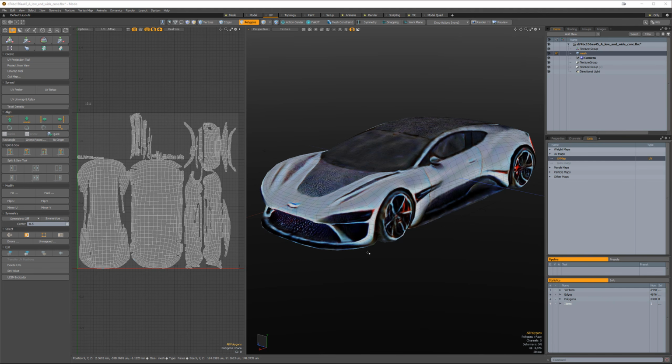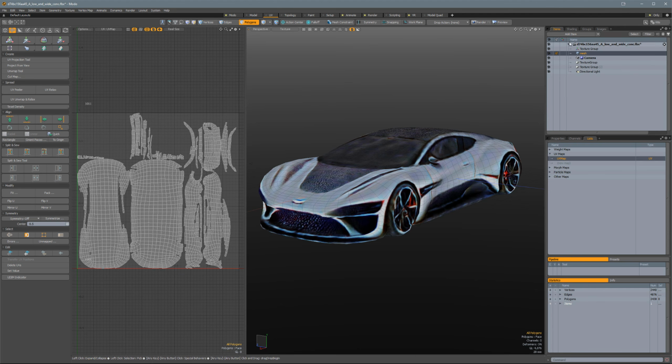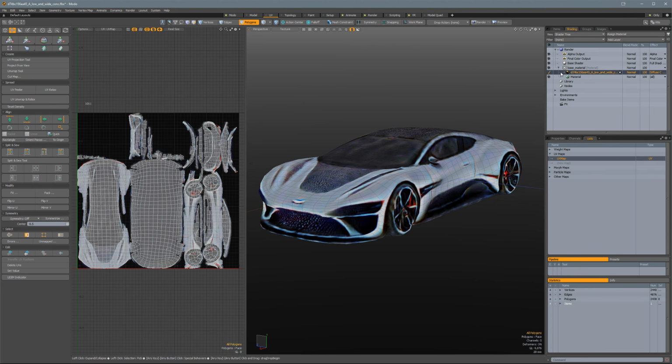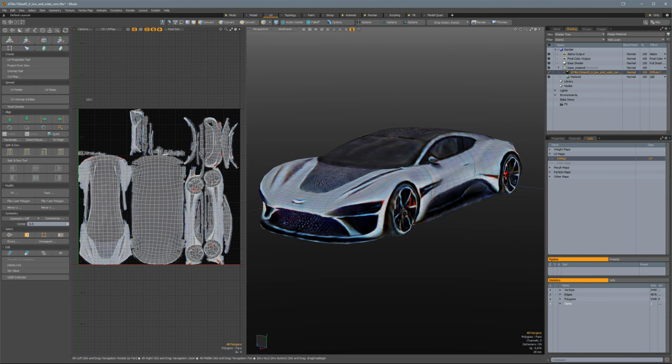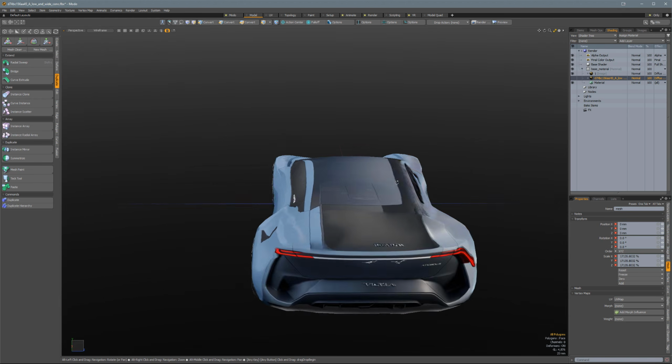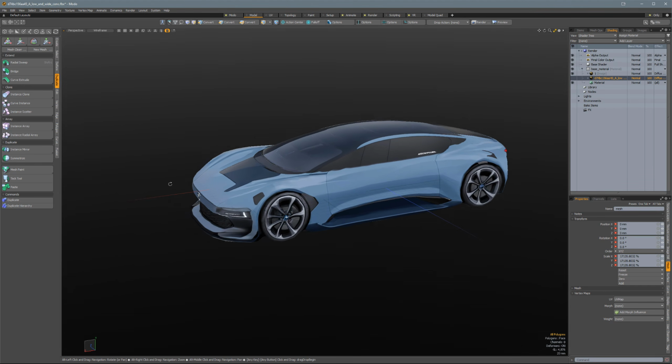So now I've just opened Modo, and I've imported the FBX file that we downloaded originally from Genie, as well as the same file that we used within Stable Projectorz. So you can see here I've got the mesh, I've got its texture here, and then you can see the UV layout that was generated during the retopology and export from Genie. So you can see the UV space coordinates and how the mesh overlays with them. So all we need to do is go find the texture we just exported. And for me, I'm just going to drag it in here and drop it right on top of this one here. So as you can see, it's not symmetrical, so it's exactly the way it was in Stable Projectorz.